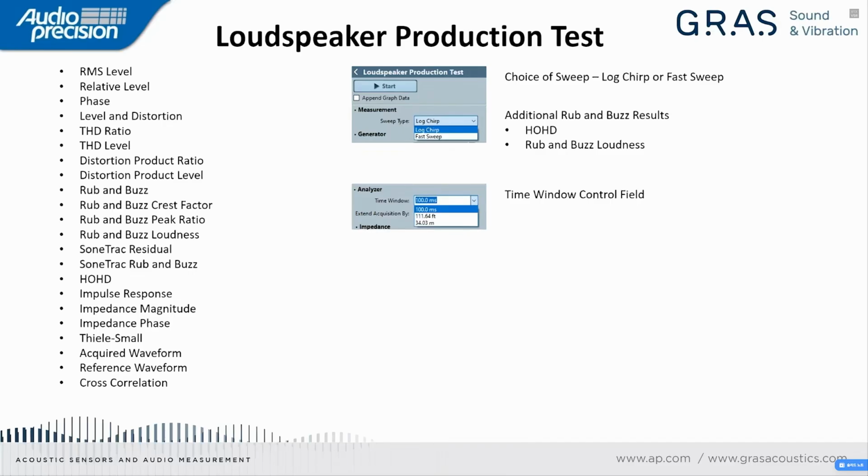Unlike almost any other field in the APX software, because the time window can be specified in distance, such as feet and meters, if you're specifying the time window in seconds, you must type the S. So in this image, you can see it's 100 milliseconds. So if you're changing this, don't just type in 50M for 50 milliseconds, because you'll end up at 50 meters.